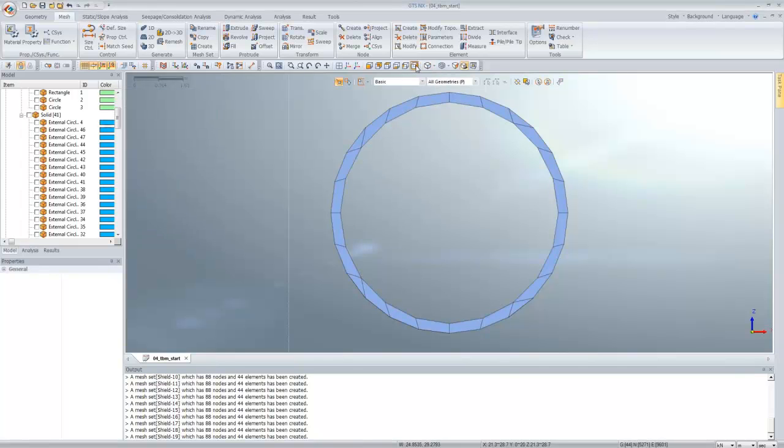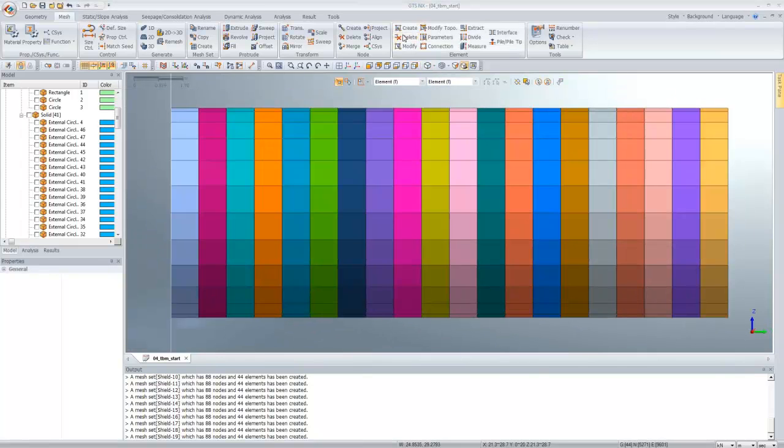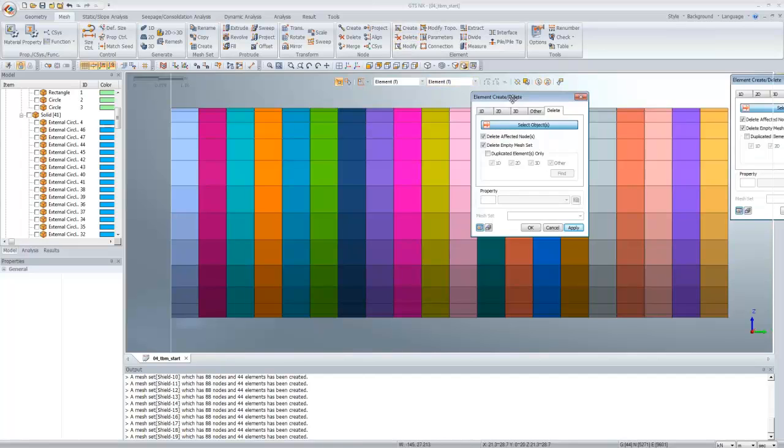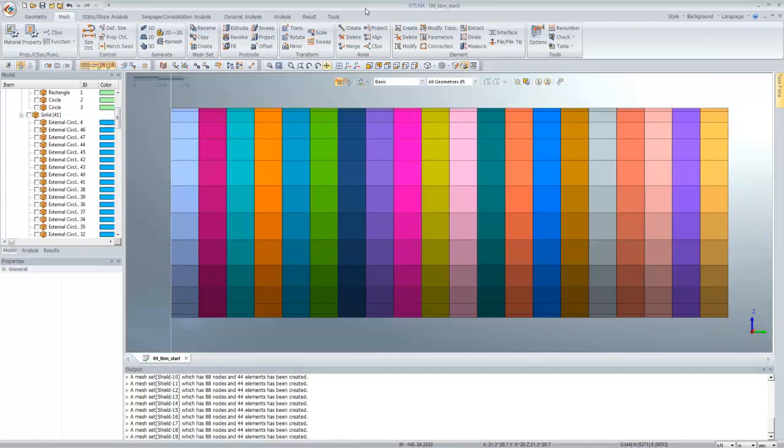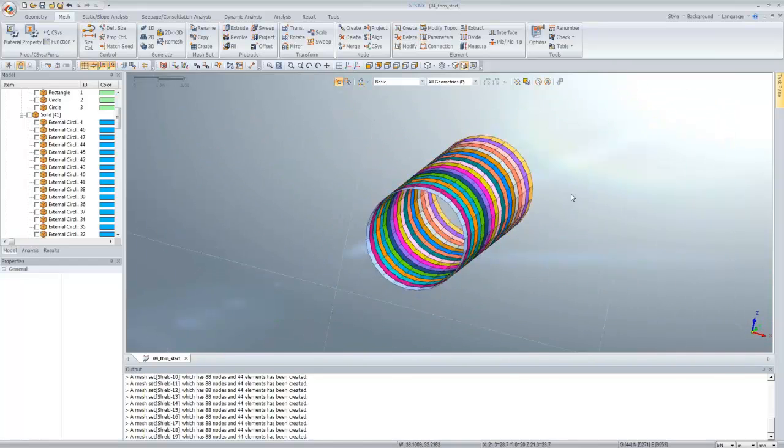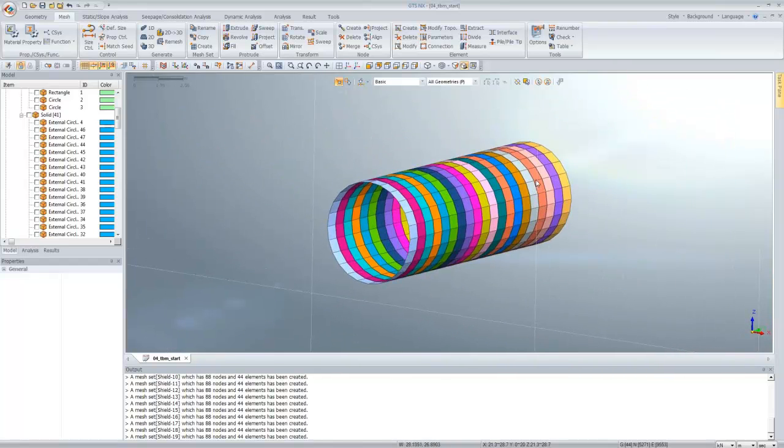OK. Now you can go to the side view, once again use the delete command and select the outer thickness area. Change the selection once again to select by single, and you can just select the outer thickness area, which I will show you after delete how it looks. So click OK, and now you can see that a thin shell element is constructed for you.